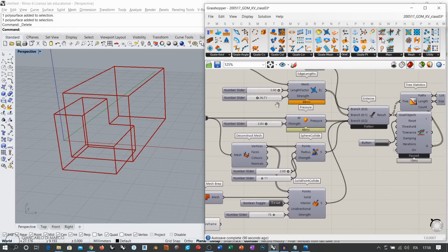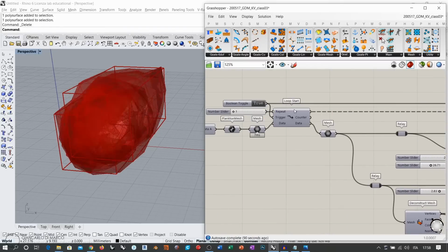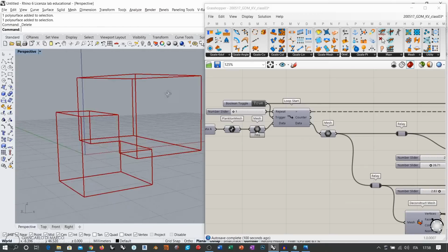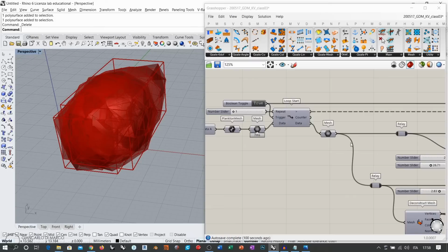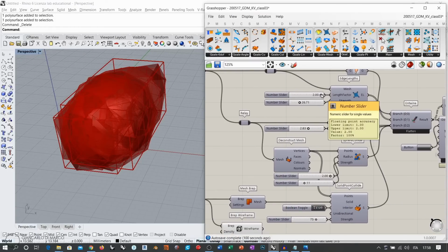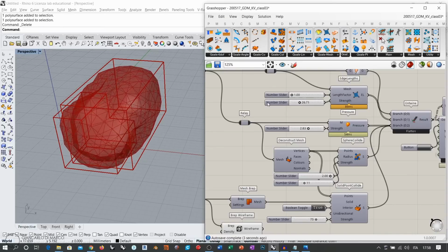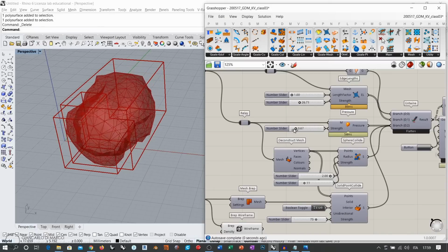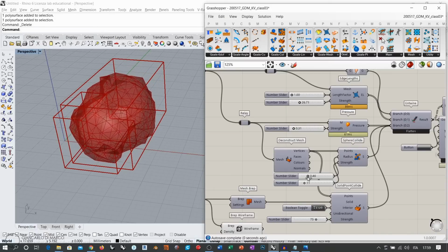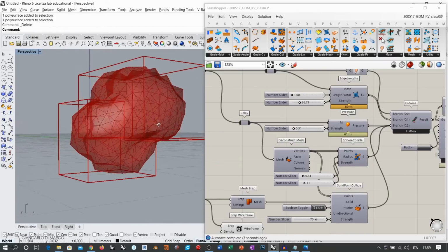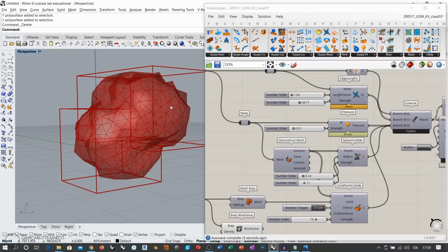If we reset everything and make this simulation run, you see that the object now is growing inside this volume in a very bad way, because we left the length factor at 2, and the pressure at 2.83. We have a radius of 2 for the sphere collide. So remember that each time you run this kind of simulation, you might want to have the values set to a smaller value. Or else you are going to have that kind of quick expansion, which will produce self-intersection, exactly like with the curves.